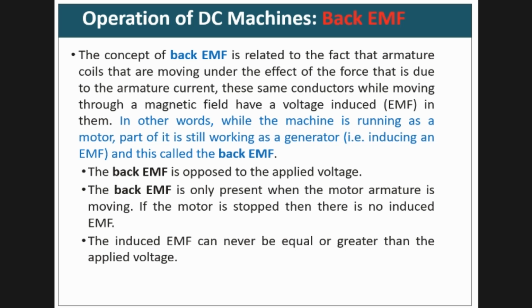So it will be inducing an EMF, and this is called the back EMF. So the motor, when it is working, is acting as a generator as well, so this will create a back EMF. The back EMF is opposed to the applied voltage. The back EMF is only present when the motor armature is moving, and if the motor is stopped, then there is no induced EMF. The induced EMF can never be equal to or greater than the applied voltage.